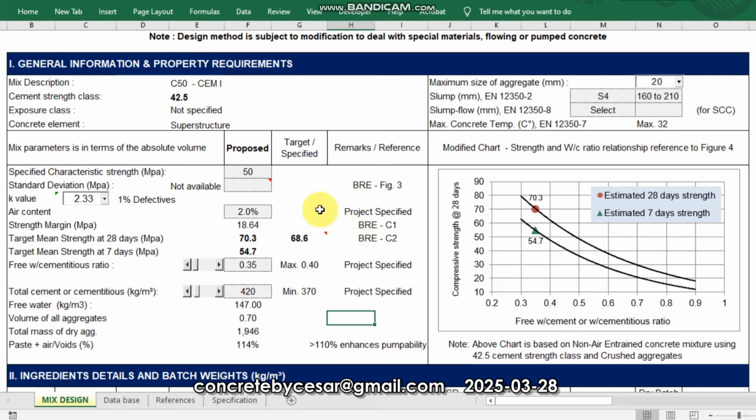Just as I told you before, if you go to a certain location where the aggregates, for example, or cement is at different scale of its quality, maybe you can still use, but you have to establish your own chart so that you can at least estimate it more precisely according to the actual strength of your materials and according to the performance of your plant and your team. So this will always reflect on the actual scenario.